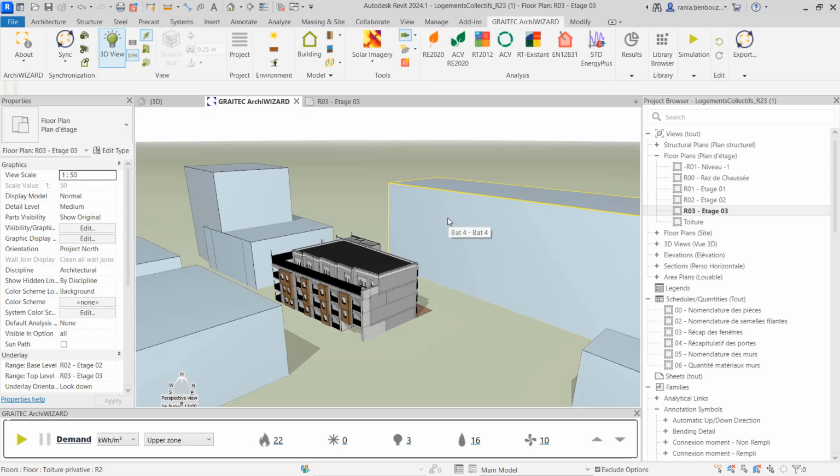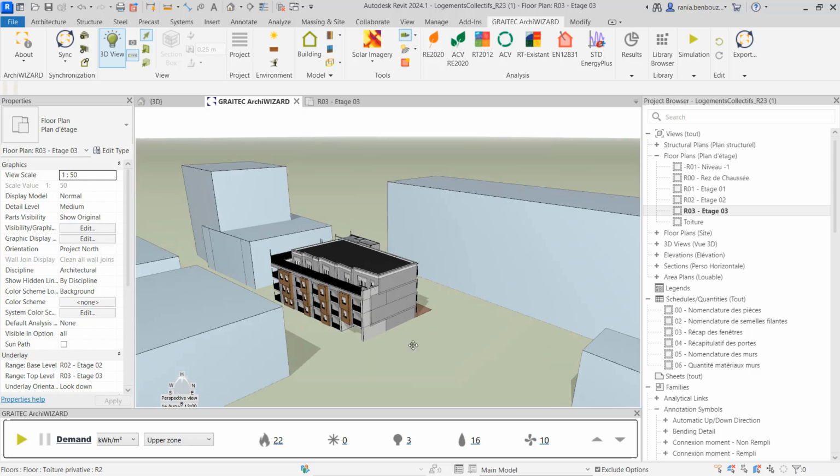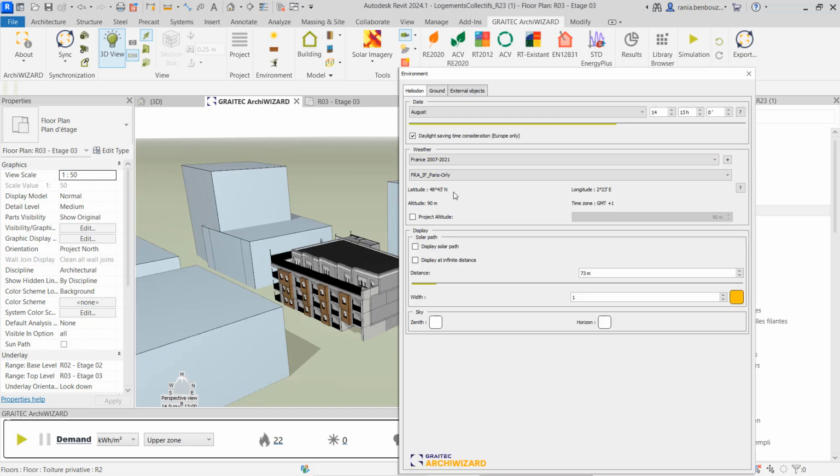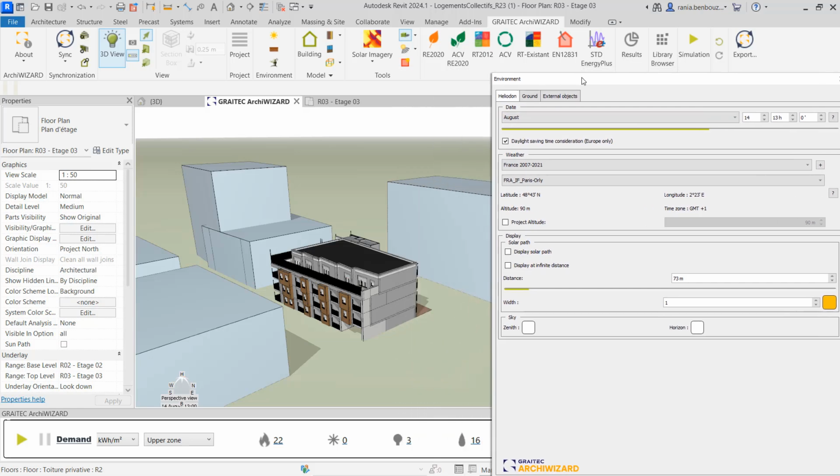Now we first need to understand the condition of the building and its exposition in order to come up with effective bioclimatic strategies. Bearing in mind that we need to consider two types of comfort in our strategy: winter thermal comfort and summer thermal comfort. Each is contradictory, because while summer comfort requires minimizing the solar irradiation through walls, winter comfort requires absorbing as much heat as we can. The weather file used is the current conditions of Paris, so we are located in a temperate climate. This means a moderately cool winter with a generally cloudy sky and a warm summer with a mean temperature of 25 degrees.